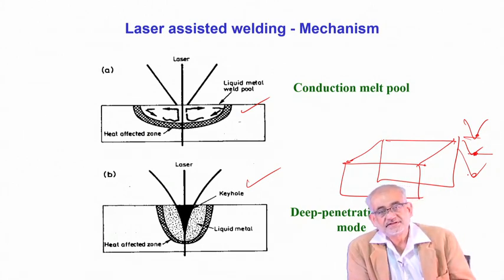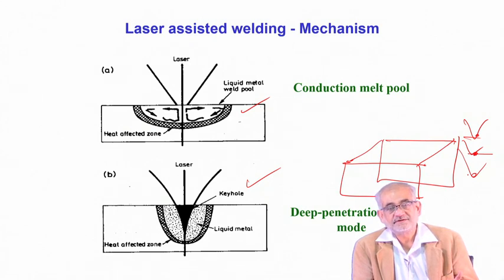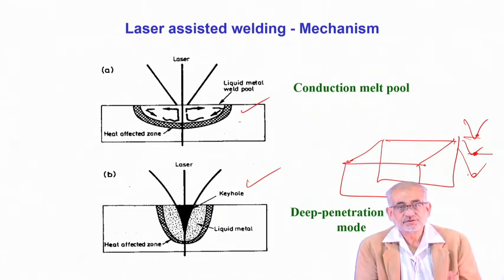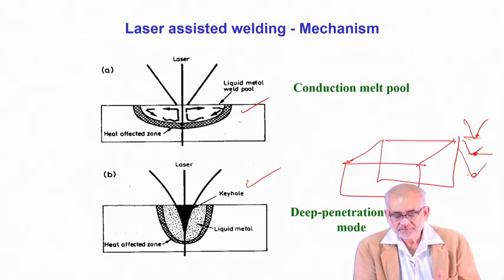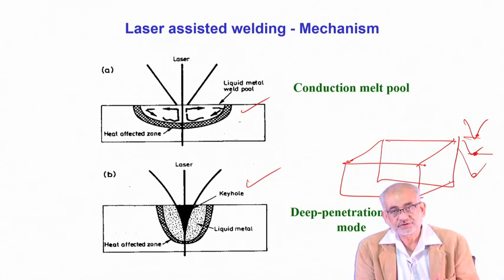One of the biggest advantages of laser material processing is that you can do either in controlled atmosphere in a confined chamber, or if it's a non-reactive metal, you can easily do everything in open air, and you can do processing where you have a very high melting on one side and low melting on the other side. So you have to have a correct strategy of joining them. But you can certainly use laser for joining.